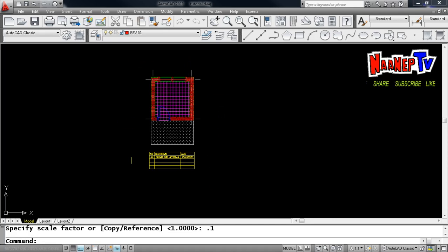So the best way is to prepare a check print. That is one purpose of the MVSETUP: make a print in the required scale or to whatever size we want to print the drawing onto.